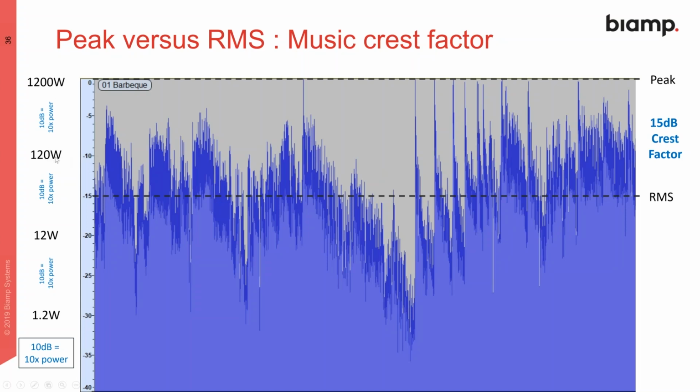So 10 dB down, we are at 120 watts. 15 dB down, well, 20 dB down, we can go 1/10 again. So we're down to 12 watts down here. Somewhere in the middle is going to be our 15 watts. So say 60 watts is going to get us the RMS for this. So 60 watts RMS, 50 watts RMS will give us our crest factor.